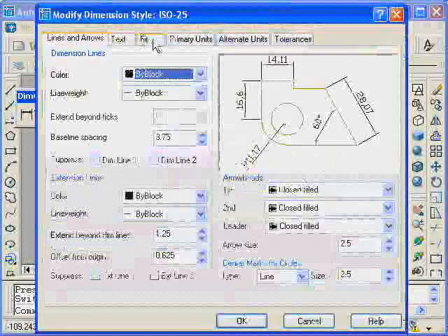and then I'll use the Shade Plot option in the MView command for the isometric view. So type MView, S for Shade Plot, and then use the hidden option. H, enter. Now I'll select the isometric viewport and press enter. If you recall from a previous tutorial, this will guarantee that the isometric view is printed with the hidden lines removed.